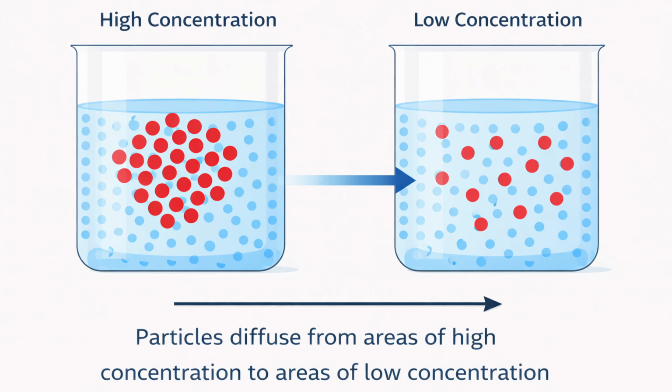The Glaser method calculates moisture movement through building components by analyzing the diffusion of water vapor, primarily using Fick's first law, which describes diffusion based on concentration gradients. It evaluates the interaction between internal and external temperature and humidity levels to assess condensation risks.